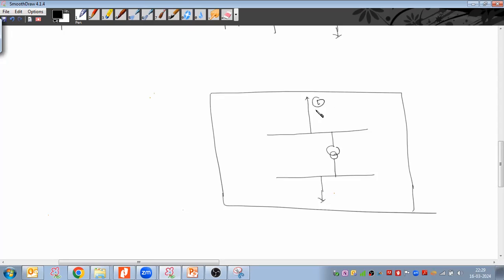It could be line 1. So this is my protection zone 1, the line. Protection zone 2 will be the bus bar. Protection zone 3 will be the transformer. So majorly we have three protection zones. And this bus bar protection zone is the common outcome of the line protection and the transformer protection, meaning both CTs interconnect and are connected to the bus bar differential protection.